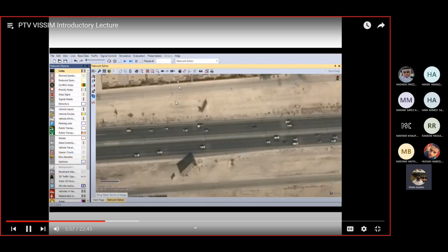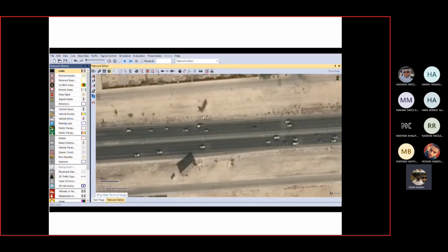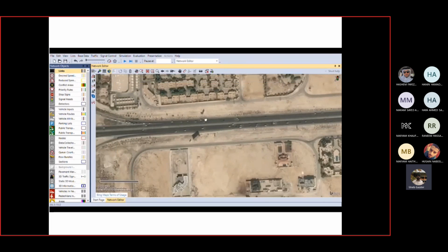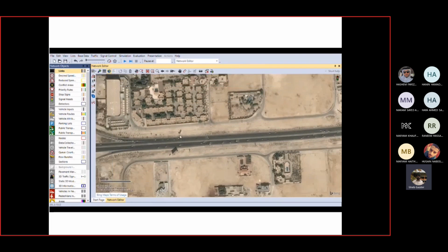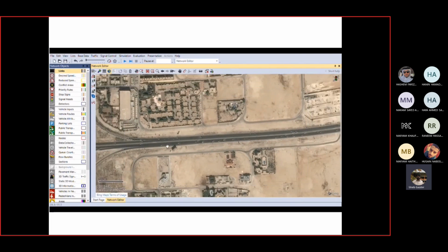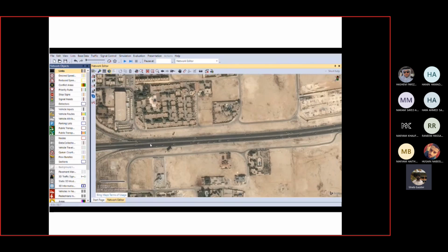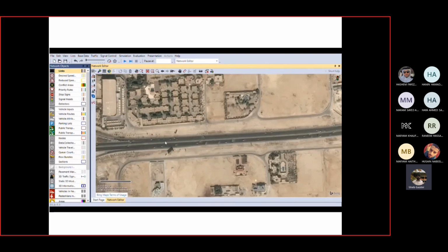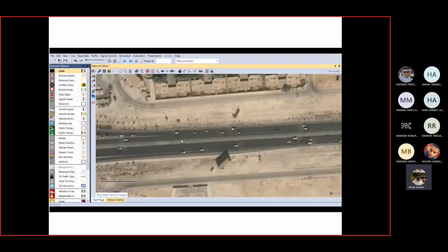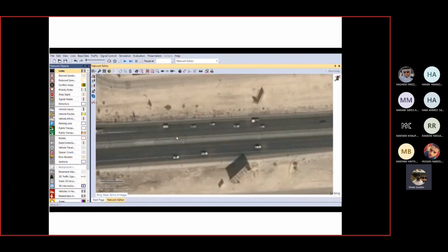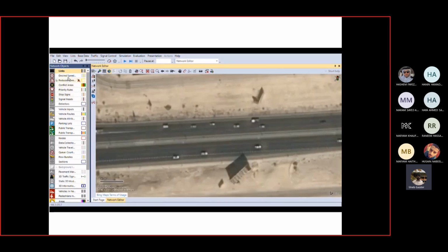So in this next part, we're going to have a look at how exactly to build our roads using links. Because we want a single uninterrupted stretch of highway, I'm going to be starting from this point on the highway, going along and finishing off over here. So we will begin by zooming in on the end of the highway that we want to build. We're going to pick links from the table of network objects.